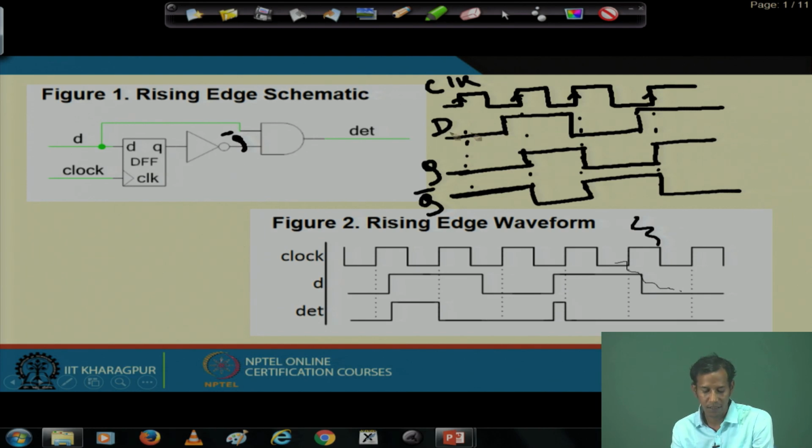Now, depending on this D input and the Q bar, if I just AND them. So, at that particular instant both are 1. So, there will be 1 1, rest of the case it is 0, then again it is 0, and here whenever this, that means for this particular time period both are 1.